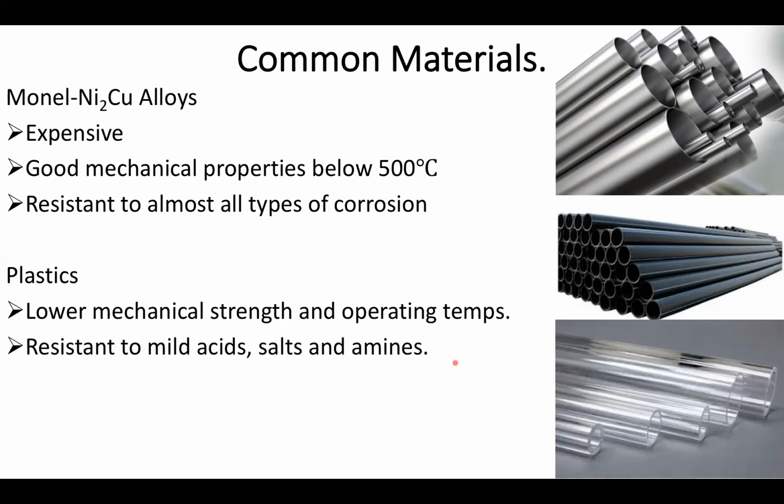However, they are very resistant to most acids, salts, and amines. So if you're working with amines or highly saline solutions, it's usually worth the move of going to plastics. However, make sure that you consult your corrosion tables to see what type of plastic you're using, as some plastics are going to be much more resistant to acids than others.